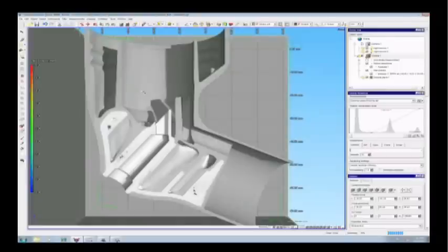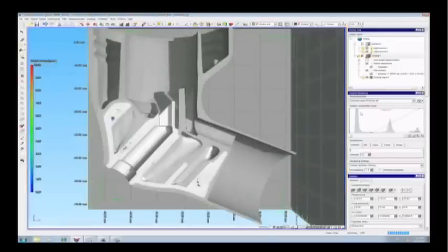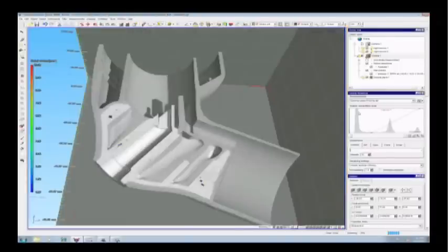Okay, that's great. In any direction, I can go in and look inside different components, segment them out based on their density. So it opens up a lot of different options. So with CT now, with one scan, I have the ability to tell the design engineer very quickly how good or bad their parts are against their nominal data set. I can tell their injection molding guys whether their wall thicknesses are good or they have voids inside their part.